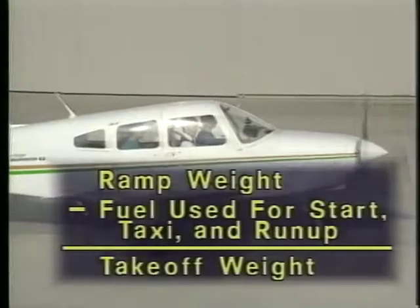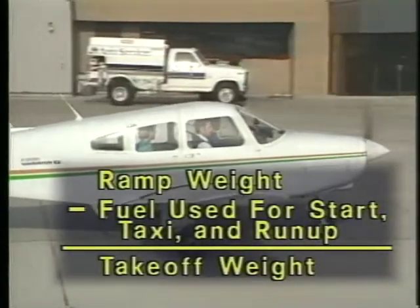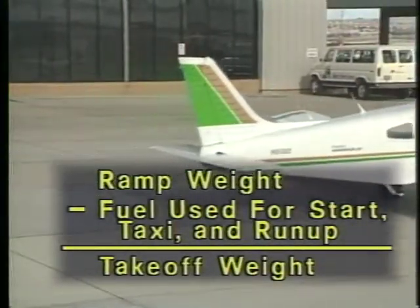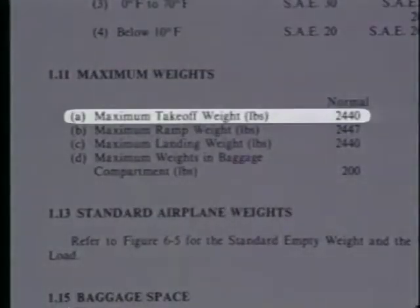You adjust ramp weight by subtracting the fuel to be used for engine start, taxi, and run-up to get takeoff weight. This weight should not exceed the maximum takeoff weight found in the POH or the weight and balance records. If your airplane is too heavy, it might have trouble getting off the ground.